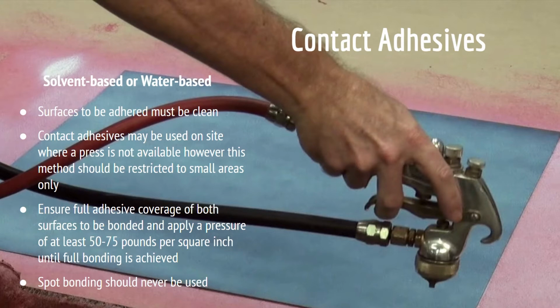There are two primary types of adhesives. Water-based adhesives form bonds when the water inside evaporates. They are better for short-term use and are more environmentally friendly. In contrast, solvent-based adhesives form bonds when the solvents inside evaporate, and they are more durable and chemical resistant.